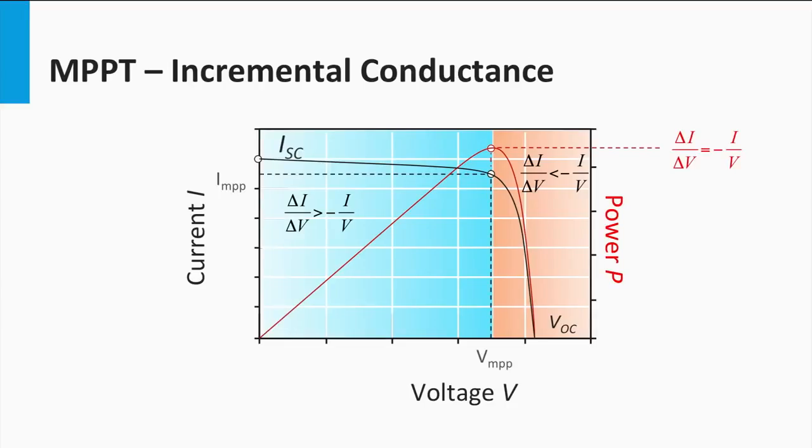This maximum power point tracking algorithm can be more efficient at the maximum power point as it doesn't hover in the maximum power point region under steady state like the P&O algorithm. Also, low sampling intervals make it less susceptible to changing illumination conditions.